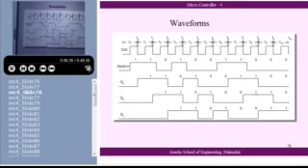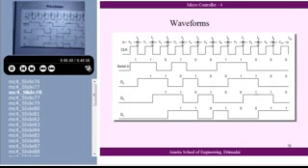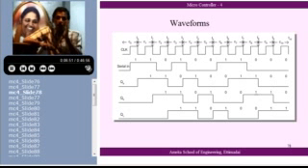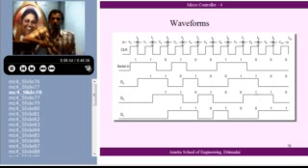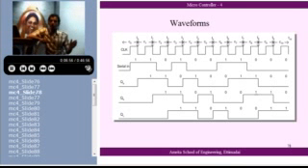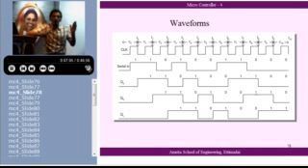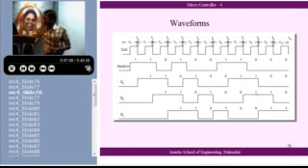So the data, whatever input data you are given here, at successive clock pulses, this 1 is getting shifted, this 1 is getting shifted, 0 is getting shifted, 1 is getting shifted. So that data stream, that 1, 0, whatever data stream I have given to the first flip-flop, is sequentially getting shifted to succeeding flip-flops in the succeeding clock pulses. This is called a shift register. It is a register where data is shifted from the first flip-flop.